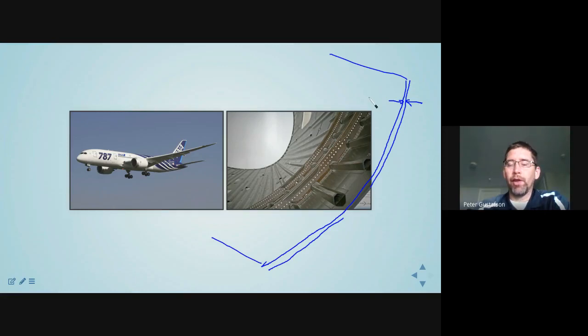Now, in circumstances like this, what we're going to find is that it is often the case that the out-of-plane stresses, that is the stresses that are oriented normal to this surface that's being generated, are going to be negligibly small. For example, if we look at the outside fuselage of this aircraft and we drew a normal vector here, so this is my attempt to draw a normal vector with a mouse. It's obviously not perfect, but it's oriented away from the aircraft. And at that surface, we're going to have a nearly traction-free surface.